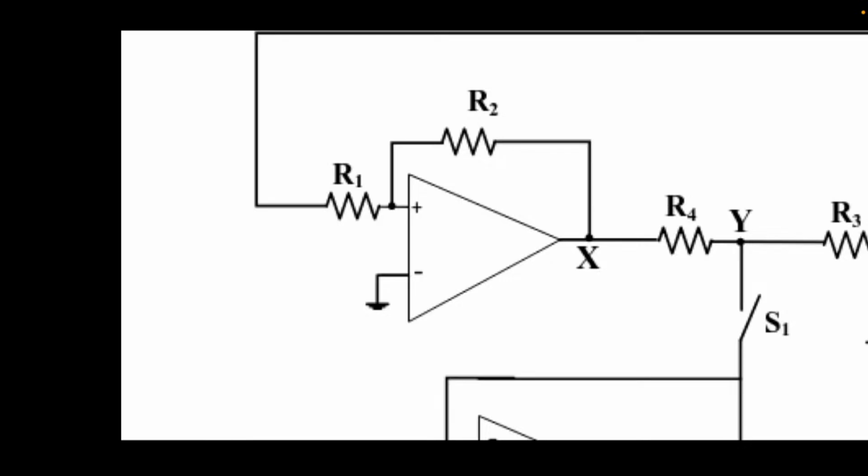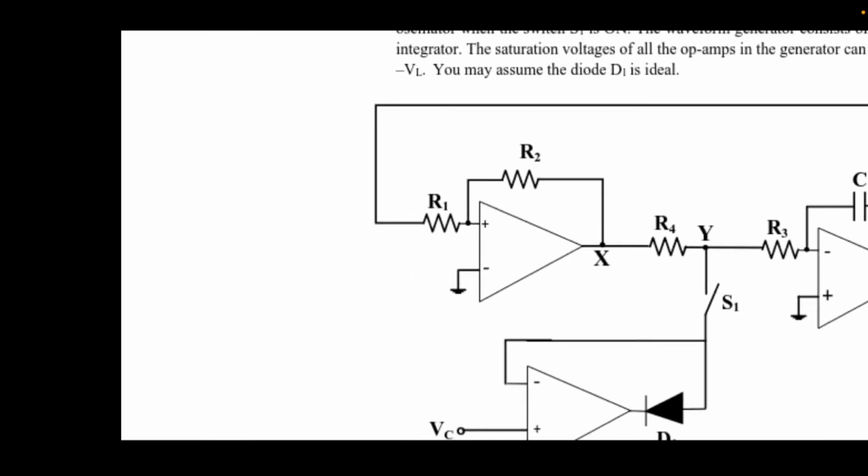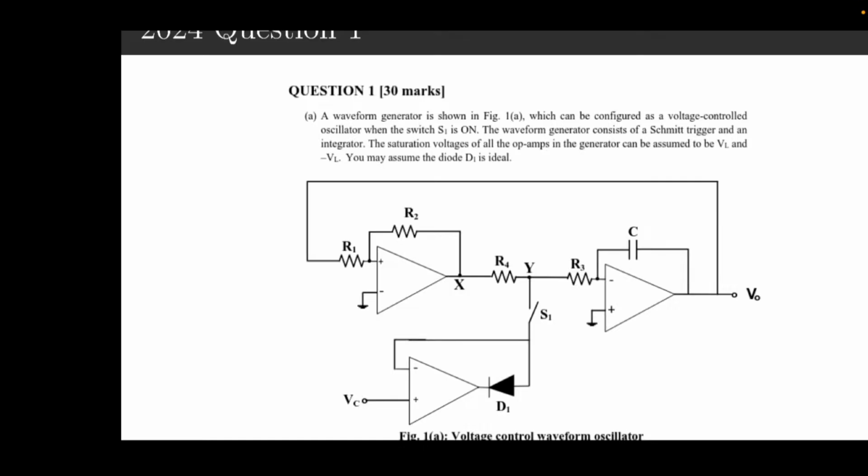What will happen is the amplifier has positive feedback, which causes the voltage at the output to saturate to positive VCC, right? Why is that? Because the difference across the two terminals is positive, right? Pretty simple. And if you have a negative voltage here, then it'll saturate down to negative VCC, right? Okay. So that's the kind of foundation for how we're going to do these questions, nonlinear amplifiers.